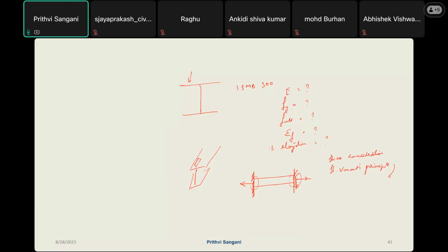If you have higher stress concentration, your strip is going to fail at this position directly. If it is failing here, then it is actually not giving you the real stresses. It is giving you a stress concentration. Usually, if you have 400 MPa acting at mid span, here your stresses will be about 500 MPa, and this is not replicating your actual scenario. So you can't use this kind of strip.